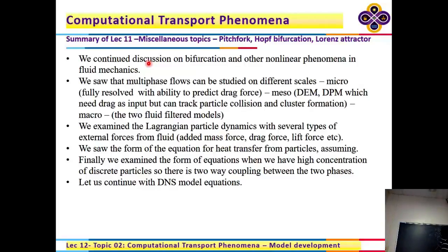So it is only this term that's non-zero. And when you integrate that, this Laplacian in one dimension, there will be only gradients of r that will appear there. Gradients in z will drop out, gradients in theta will drop out, even though this del square is a three-dimensional Laplacian operator, right? So you will get the equation, something like this, one will simplify to 1 over r d/dr of r v theta equal to 0.